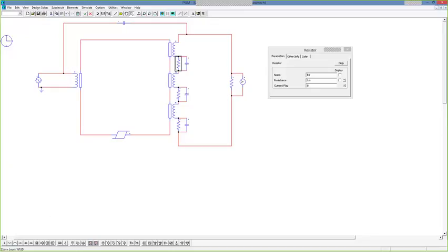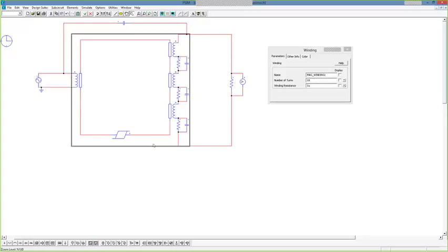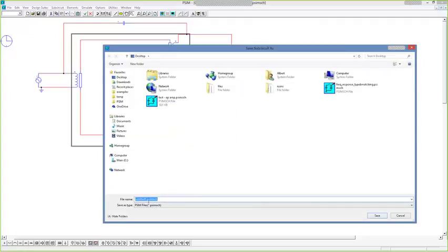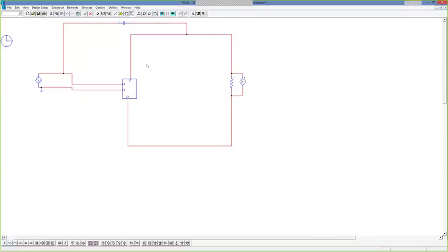So we can look at parasitic capacitance, ringing types there, input to output parasitic capacitance, and we can push this down into a sub-circuit if we feel like. So just highlight everything, right-click, and then create sub-circuit, and then this is TX sub. Just give it a name, and then it just pops down. Fun.